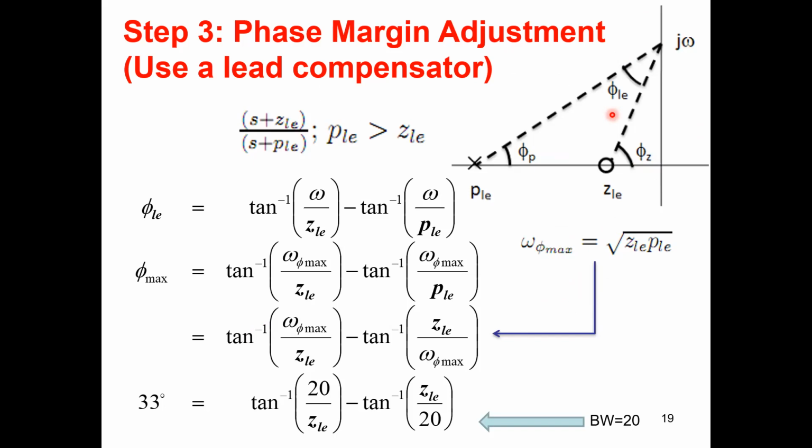You precisely design for that, because you know the phase lead compensator increases the phase addition to the plant when you increase frequency, but only up to a certain frequency, where you get the maximum phase addition, and after that it will roll off again, reducing the phase contribution as you increase the frequency.